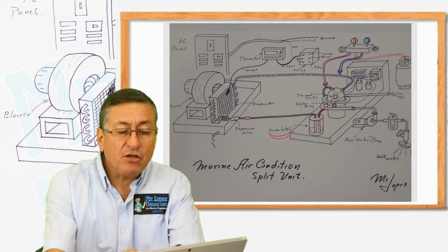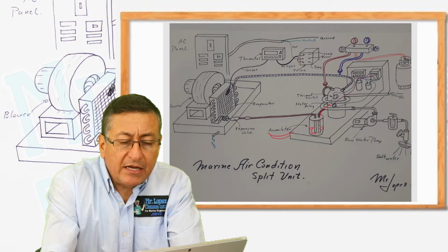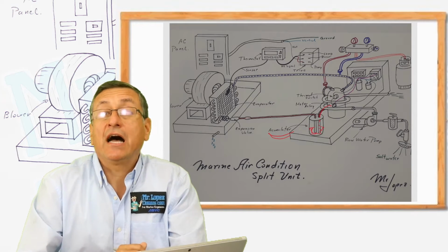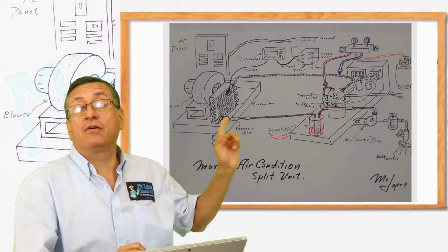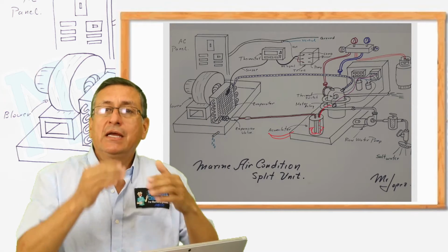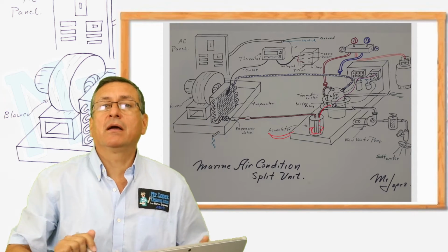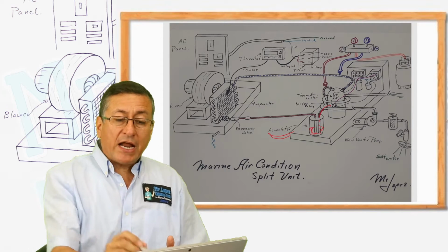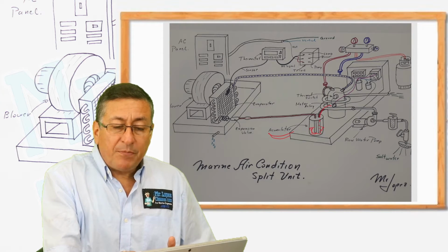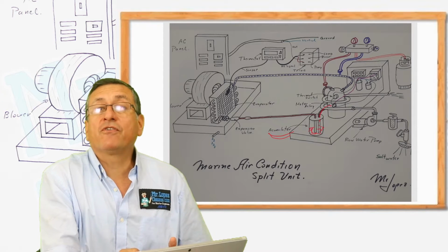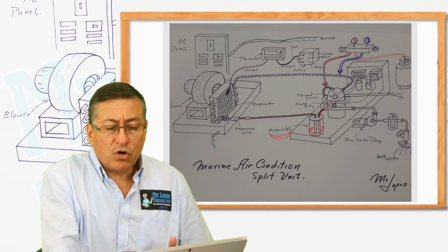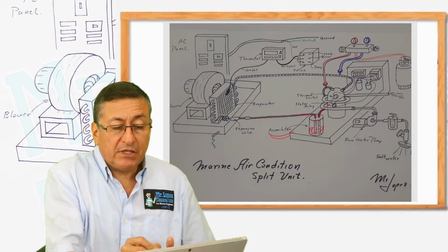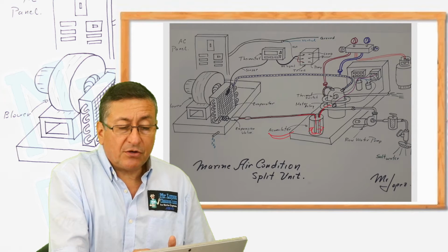Yes, inside of the accumulator in this area, in the bottom, is located a hygroscopic substance. Right now in the micro video clip we are going to check. I have a cutaway receiver and we are going to check that element internally. Alright, the refrigerant enters as vapor and in the bottom starts the process of condensation. In other words, in the output it is liquid at high pressure, high temperature.